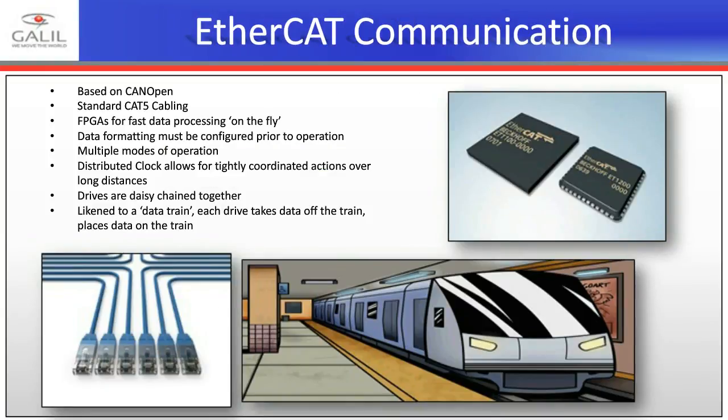EtherCAT communication based on CANopen. The EtherCAT standard encompasses a lot of different communication methods. For the purposes of this webinar, we'll be focusing on CANopen over EtherCAT, or CoE. CANopen is an automation network protocol.